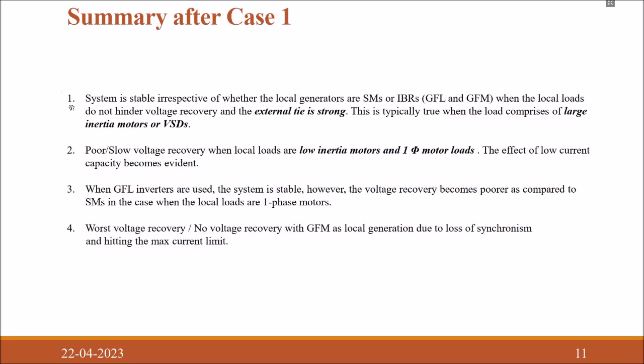So after this first case, let's talk about the summary. Irrespective of synchronous machines or inverters, whatever the generation type, if we do not want to hinder the voltage recovery in a strong grid, this is only possible when we have large inertia motors or variable speed drives, because low inertia motors or single phase motors, which have lower inertia constants, have a slower and poorer voltage recovery.